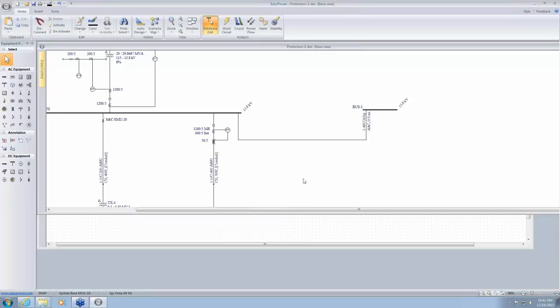Okay, so since this is open air, the conductors are going to be fairly widely spaced, and most likely the only type of arc faults that you might be getting is a line to ground fault while somebody's working on it while it's energized.